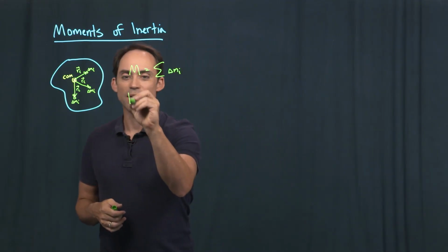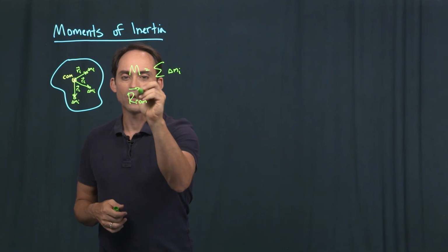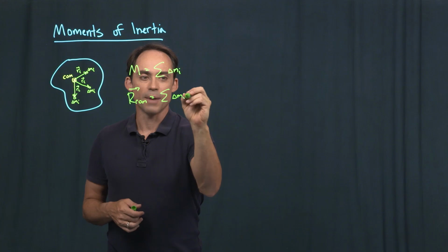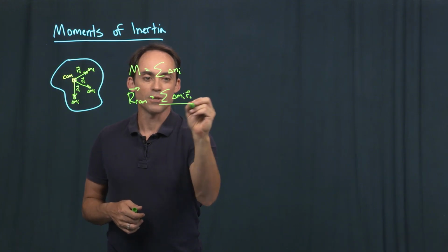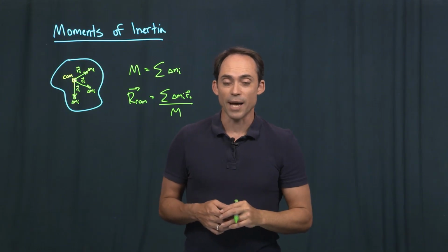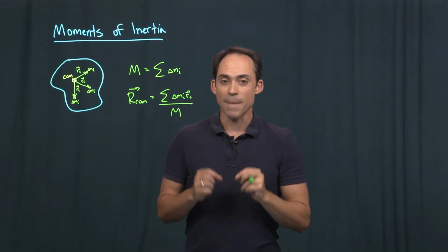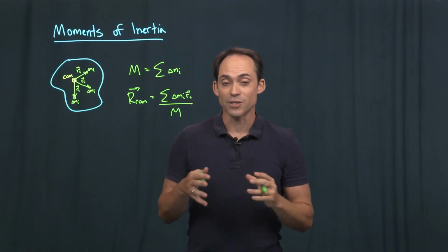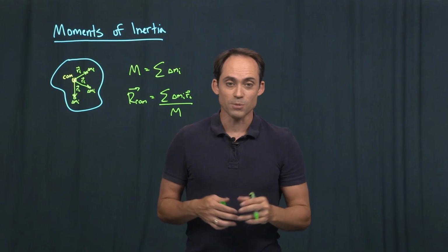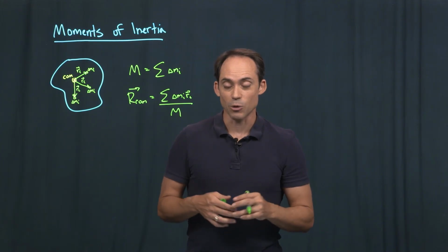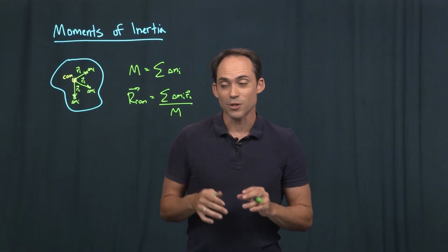We've also seen the center of mass, which is a vector quantity, and that's just adding up all of the little mass elements times their position within the object, and then dividing by the total mass of the object. So this is kind of a mass-weighted position inside the object, and it literally gives our center of mass. And this is where, of course, many of the body-centered forces like gravity or weight act on when we're looking at an object in motion. That's the first sort of moment.